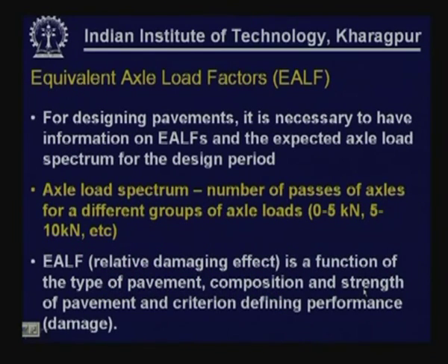For designing pavements, it is necessary to have information on the equivalent load factors for any particular load group that we want to convert into equivalent standard axles, and we also need to have the expected axle load spectrum over the next 20 years or 15 years. How many repetitions of a certain load group, 0 to 5 kilonewton, how many repetitions, 5 to 10 kilonewton, how many repetitions, 10 to 15, how many. This information is required. Somebody has to make projections about this, and we also have to have equivalent load factors so that we can convert each one of these load groups into equivalent standard axle load repetitions.